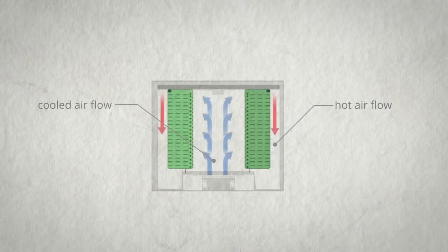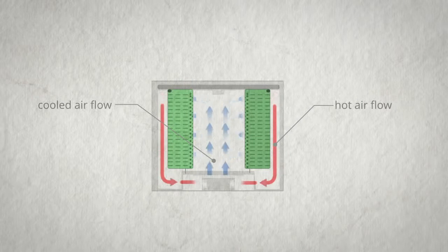Once you have the ability to measure and manage your PUE, the first step in terms of reducing your data center energy load is to focus on the management of the airflow. The most important thing here is to eliminate the mixing of the hot and the cold air. And there's no one right way to do this. Containment can be achieved through many different approaches.